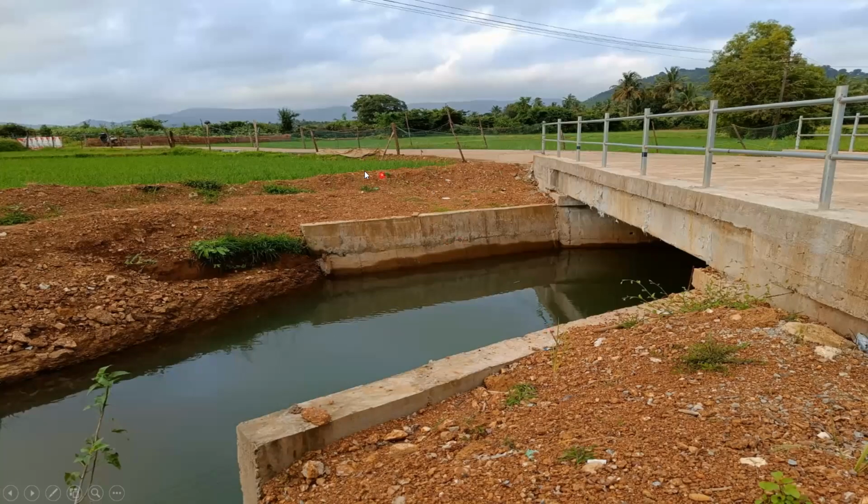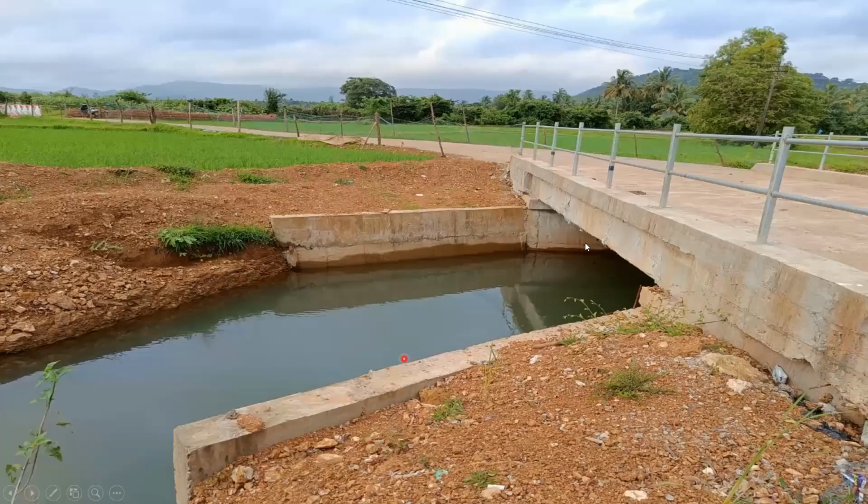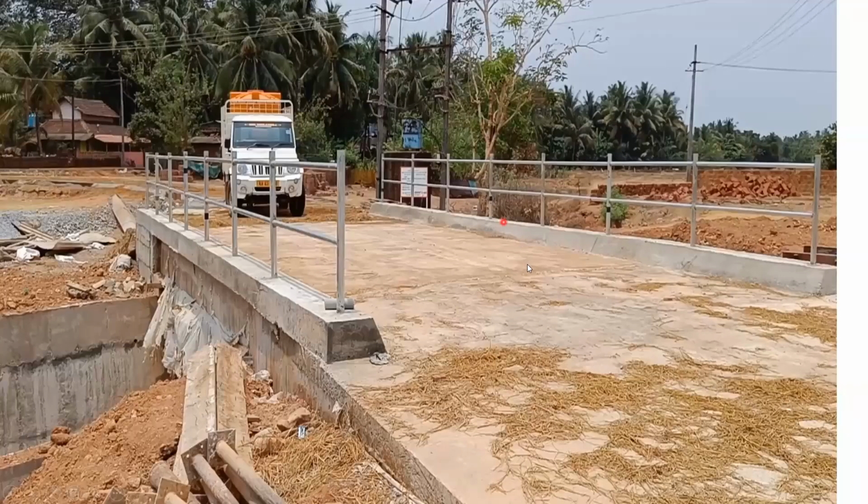Because whatever backfilling soil we had done, this was a backfilling soil. If you don't create this, the soil will fall here. And also, by doing this, you are giving a proper way for the water to flow through. So that is why this particular wing wall will be created, and this is how it looks. The water from this area is going to come, and this is how the movement will happen. You can see that hole here also, right? Whatever pressure will be created will be released. Whatever water will be there will be released. And finally, this is how the entire culvert is going to look.